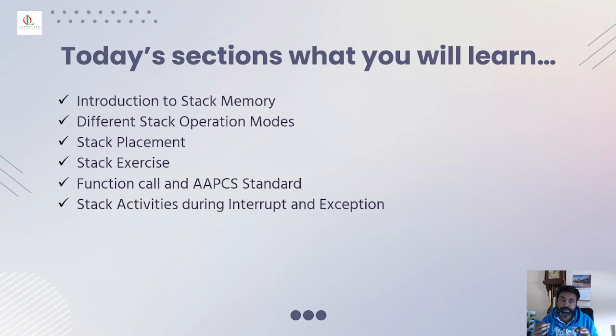You'll go through it step by step, understanding how the stack is used in your program, and then you will jump into learning about what a function call is and what the AAPCS standard is. There is a standard which is used for function calls. AAPCS stands for ARM Architecture Procedure Call Standard. And then you will learn about different stack activities, what happens when an interrupt or an exception occurs.